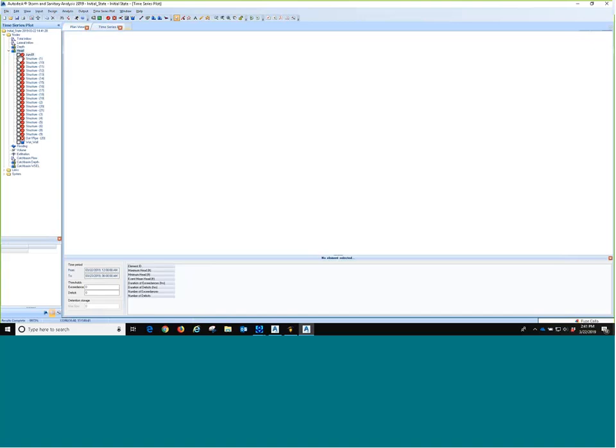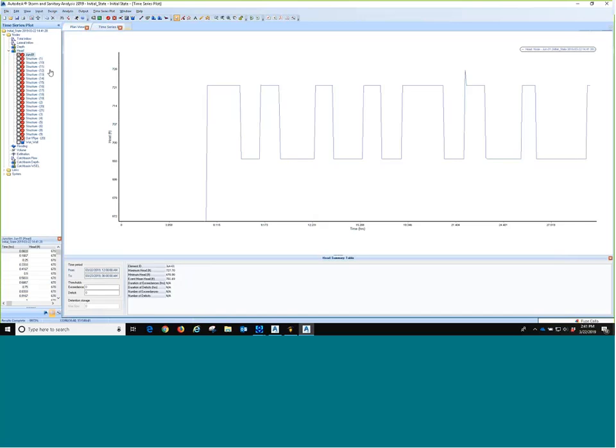So if I look at head, here's the head right at my outfall, or excuse me, right at the downstream node. There's the elevation I need to meet for static head. So up here, the difference between here and here is the static head. And then it looks like I need an additional 11 at 80 gallons per minute. I need to basically have an additional 12 feet of head pressing it out.